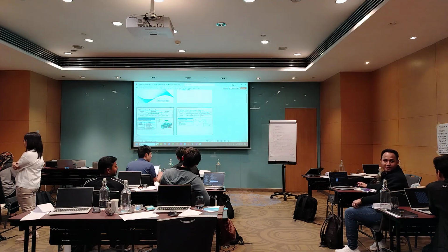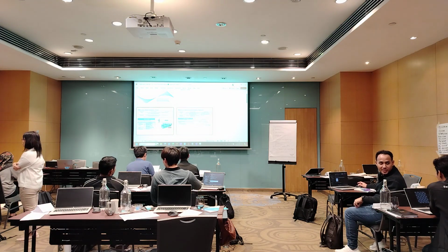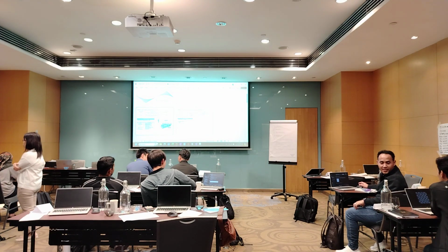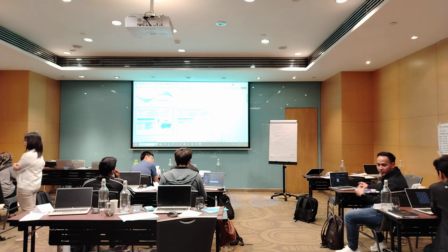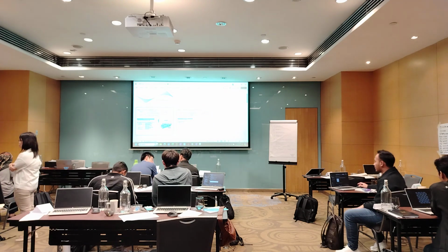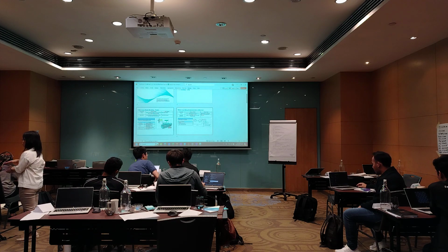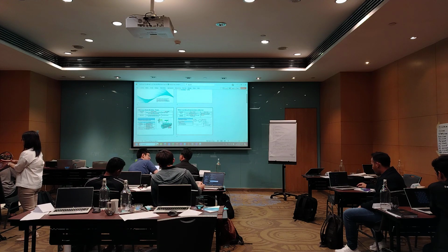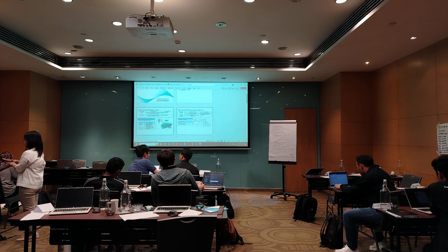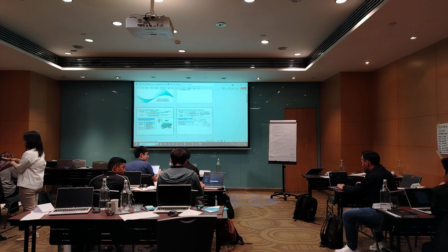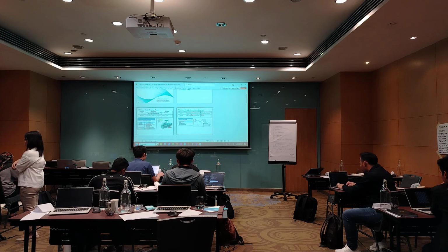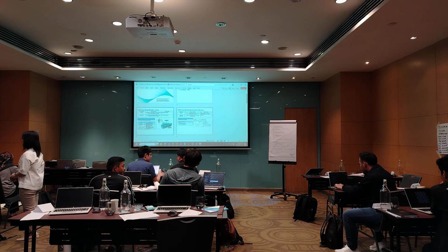But for the seal system, you just need to monitor. You just ensure that the lubrication is okay. If your lubrication is out, then your seal is also out. Because your seal face is already going together with other components. So you have to ensure your lubrication is okay.